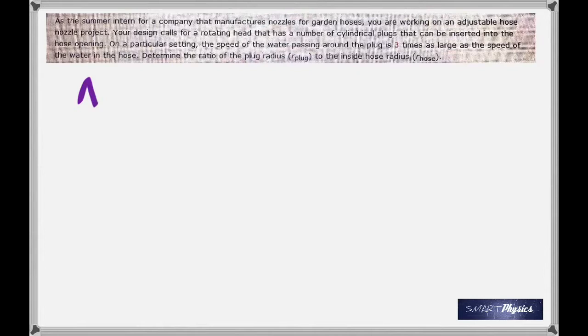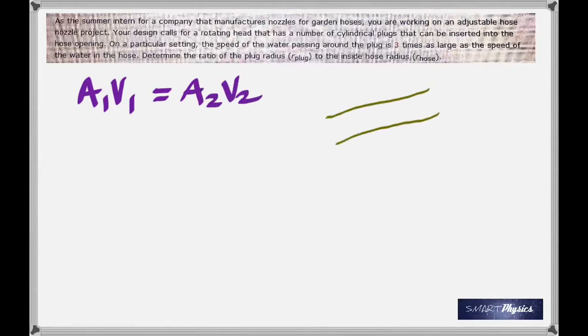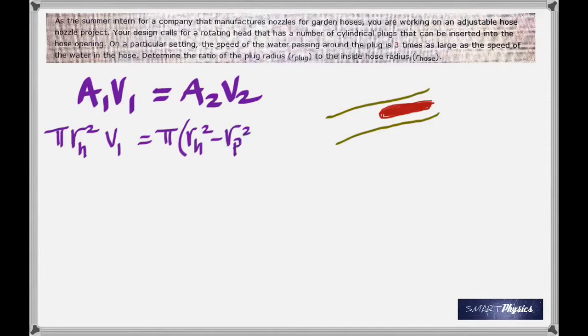Definitely what we have to use here is the equation of continuity, according to which A1 times V1 is equal to A2 times V2. If this is the diagram, a rough sketch, and that is the plug, you see that where the area is A1, the speed is V1, and where the area is A2, the speed is V2. And area is given by pi r squared. So pi r, that's the radius of the hose squared, times V1 is equal to pi times the radius of the...